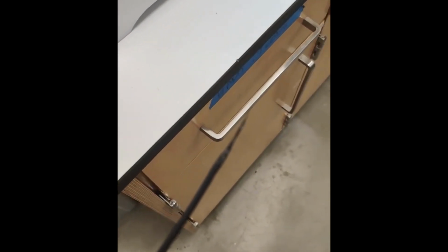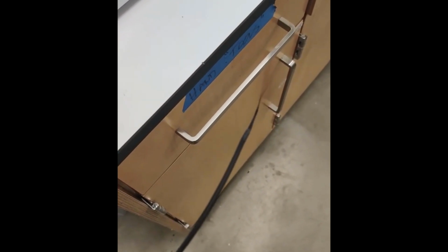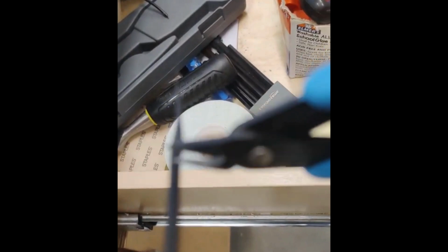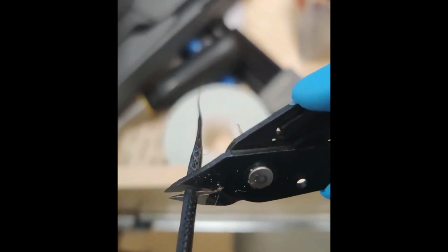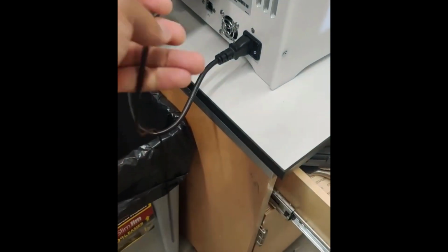Okay, and then first we want to make sure that the PLA isn't elongated and flush like that. That might cause problems when it's trying to extrude. So we're going to use some flush cutters here to snip off the weird broken end, just like that. You usually want to cut at a 45-degree angle if you can help it. Sometimes it's easy, sometimes it's not. It's not so easy here because this is tougher PLA than many of the others.